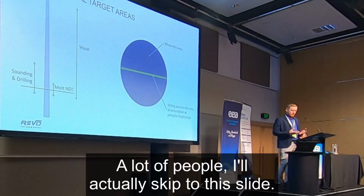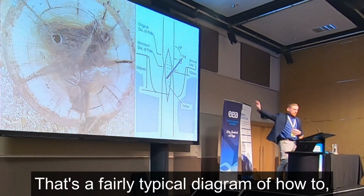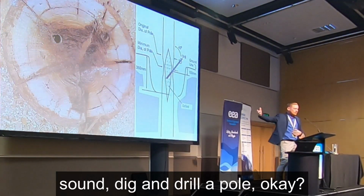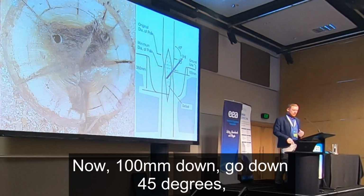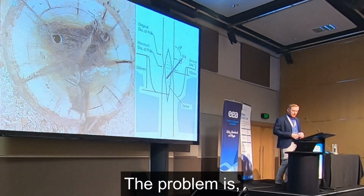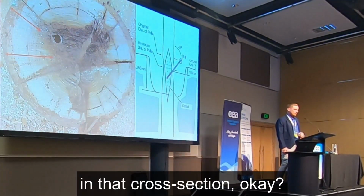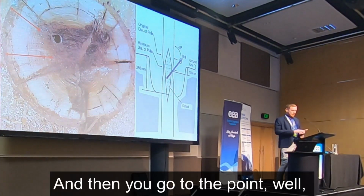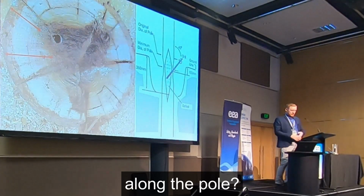I'll actually skip to this slide. That's a fairly typical diagram of how you sound dig and drill a pole. Okay, 100 mil down, go down 45 degrees, put a scraper in, feel around, take a good wood measurement, and away you go. The problem is, where are you drilling in that cross section, and how are you defining where you're drilling in that cross section? Okay, and then you go to the point, well, okay, where am I going to drill vertically along the pole?